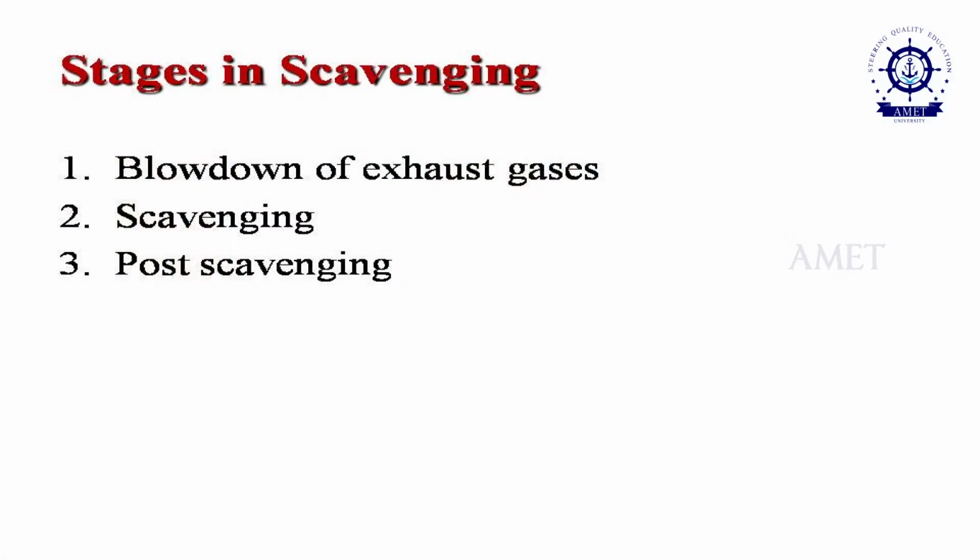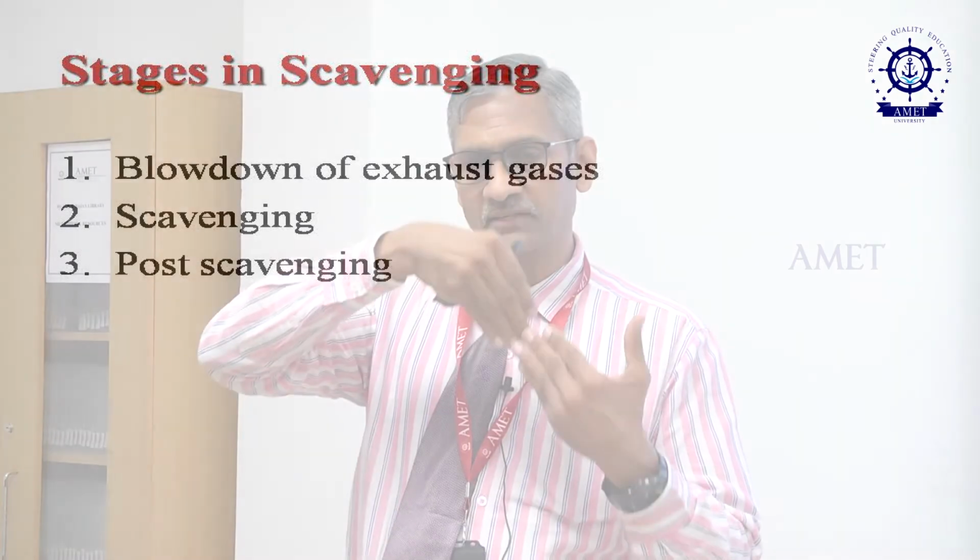The turbocharger is going to have the exhaust gas coming in, so there is a wheel and it has turbine blades, and on the other side you have the blower. There is an inlet volute casing and then the air comes out of the inlet volute under pressure and goes into the manifold. Okay. So, because of this you will have the power increasing and the torque increasing in the unit.